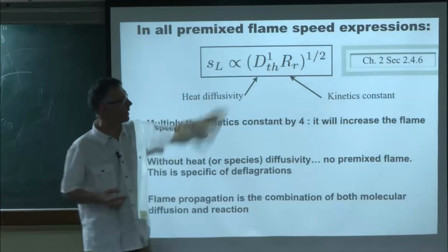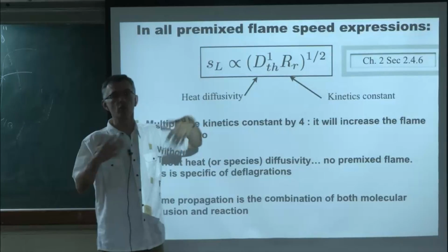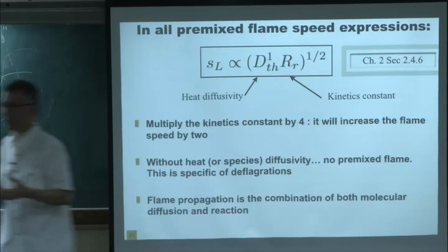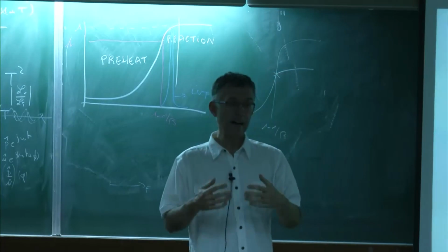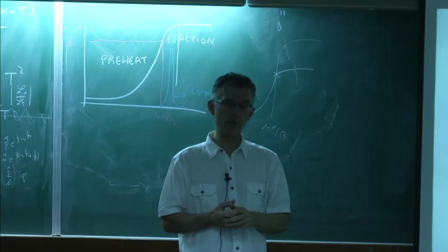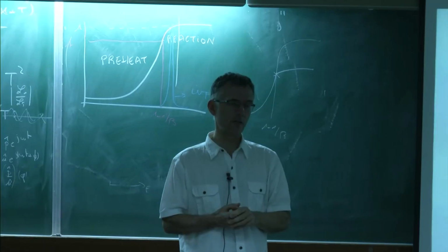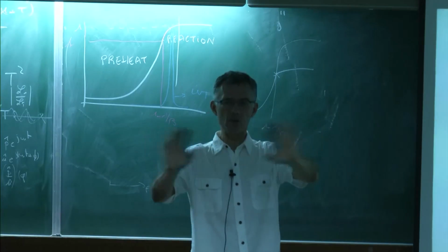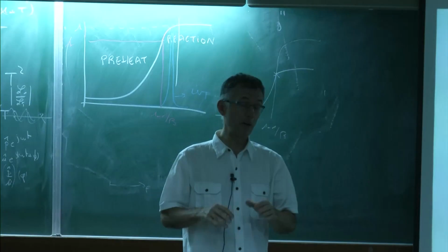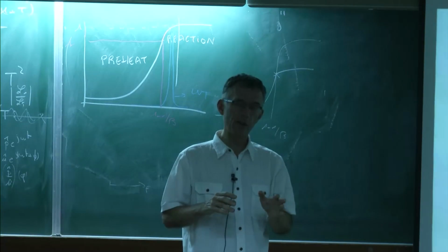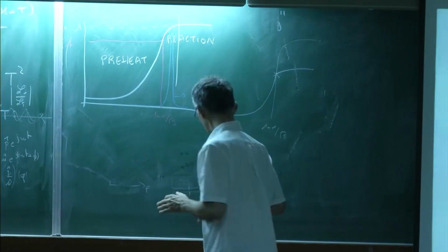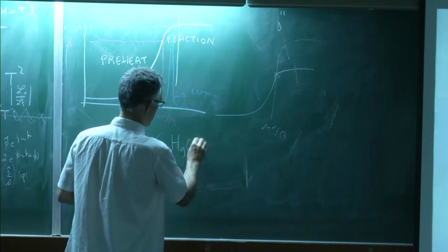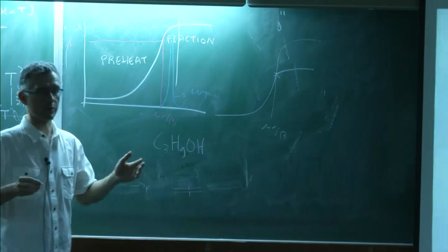Of course, here, it's a very simple model, so there is only one diffusion coefficient. But in the real world, the diffusion coefficients of all the species are going to be critical in your flame computation. And now, if someone gives you a scheme with 2,000 species and tells you, I've done everything, you got all the reactions, you have to tell him, okay, what about the mass diffusivity of this very nice intermediate species that you've put there?